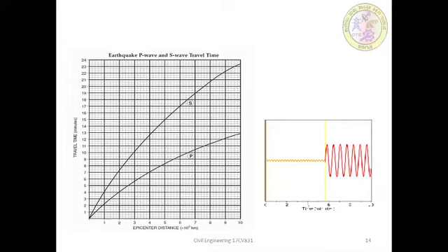So here it is. According to this, after looking into the earthquake travel time graph, it is clear that the two curves have a difference of 5 units in the y direction. So we have to search here. Whatever the S and P is, we have to count that 5. Looking into the earthquake travel time gap, whatever the x is, that is the epicentral distance, and it works out to 3.4.